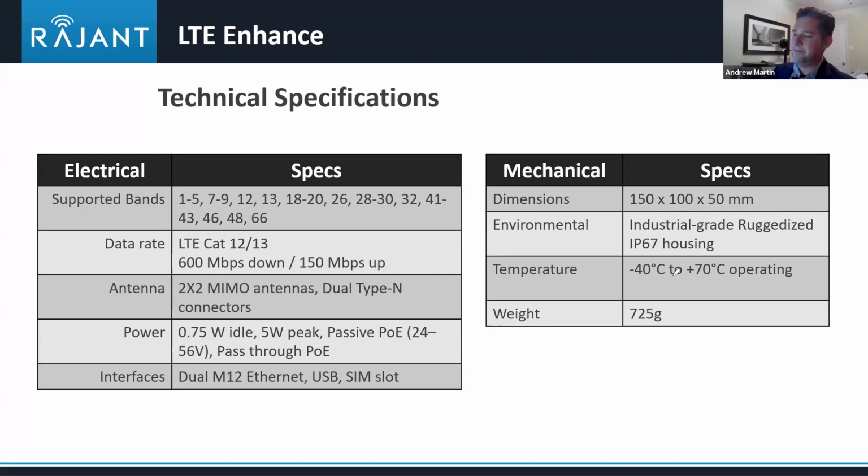I actually have the device here. Some of the other things that I have on the electrical side. So with the device, on the top, you can see these are the two antenna ports, these are the two N connector ports. On this side, I guess that's my left side, that is a port for USB. The communications for this is communicating to the breadcrumb with USB, and this is an M12 connector. It's A-code, and that's the connection between the breadcrumb and this LTE device.